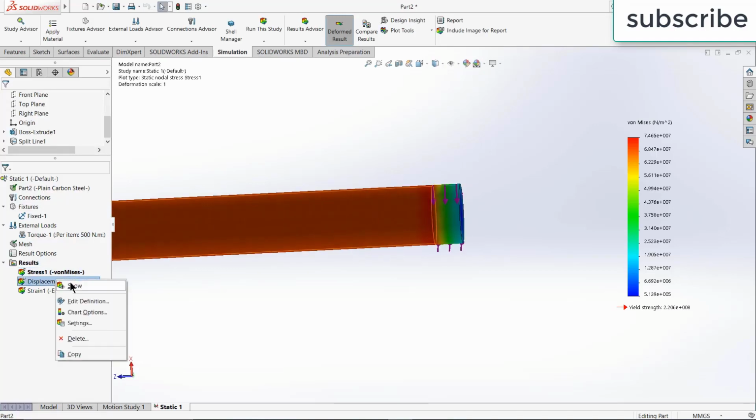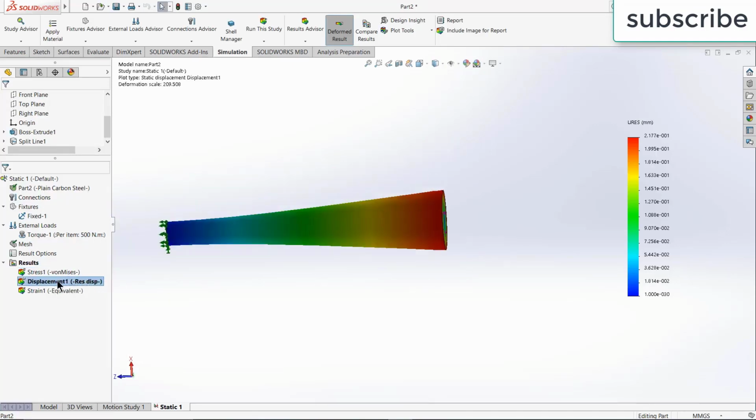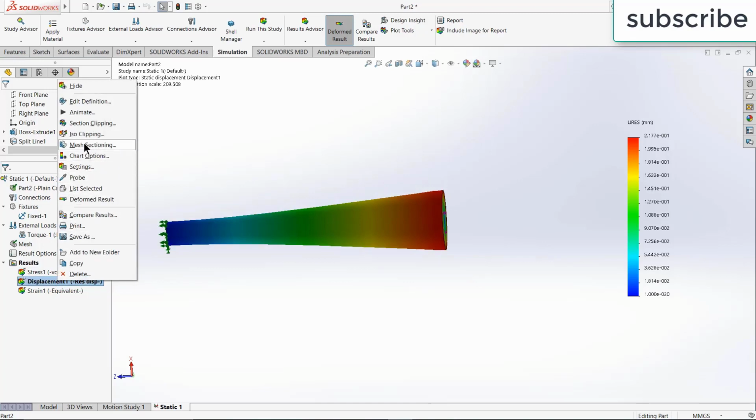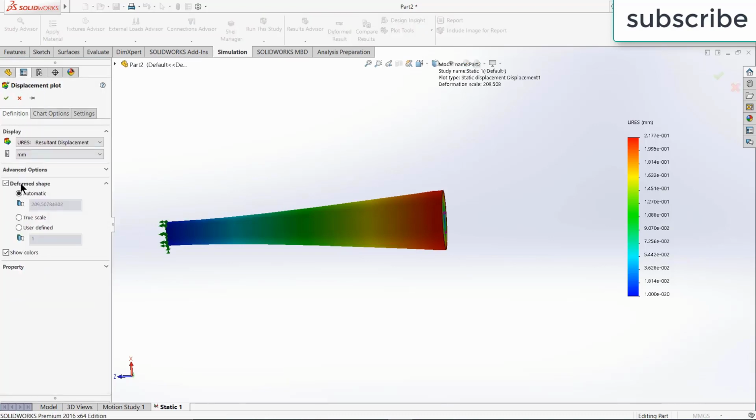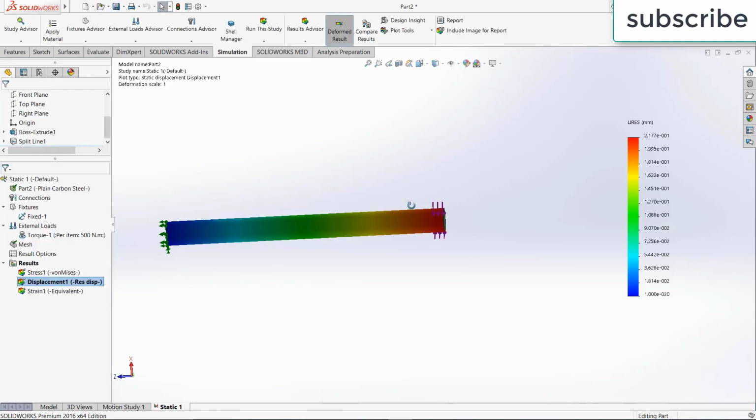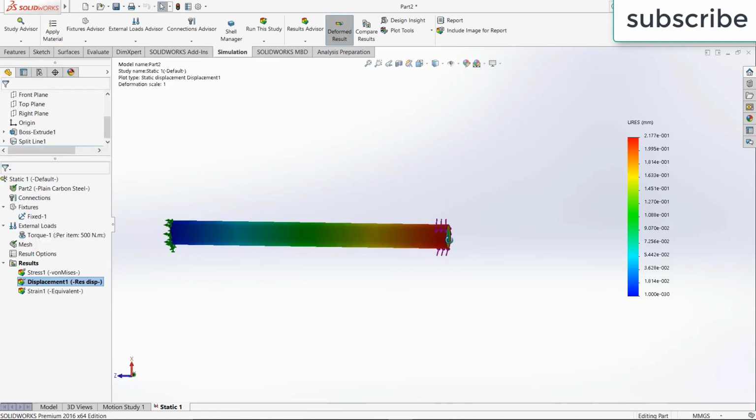And if I right click on displacement, click on show, again right click on it, click on chart definition, true scale, click OK. So here you can see, this is the maximum strain.